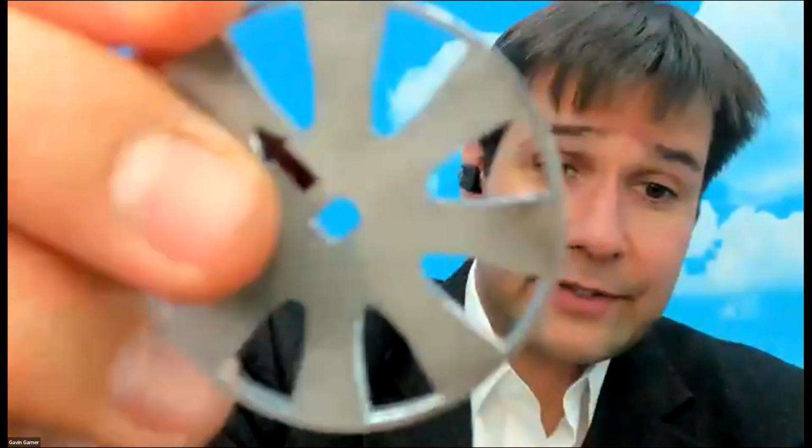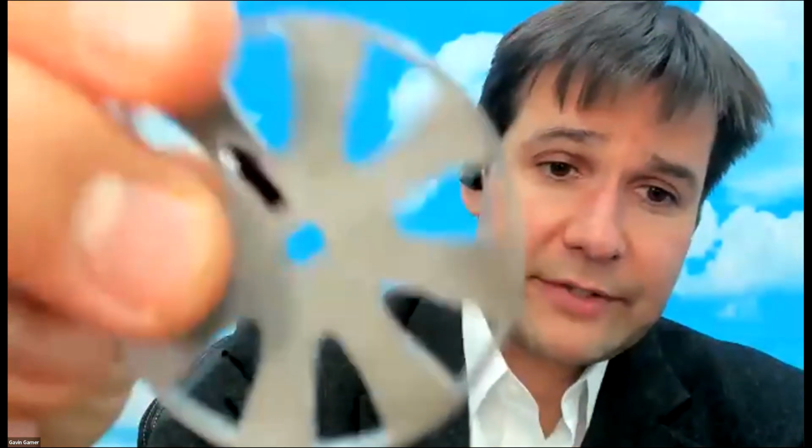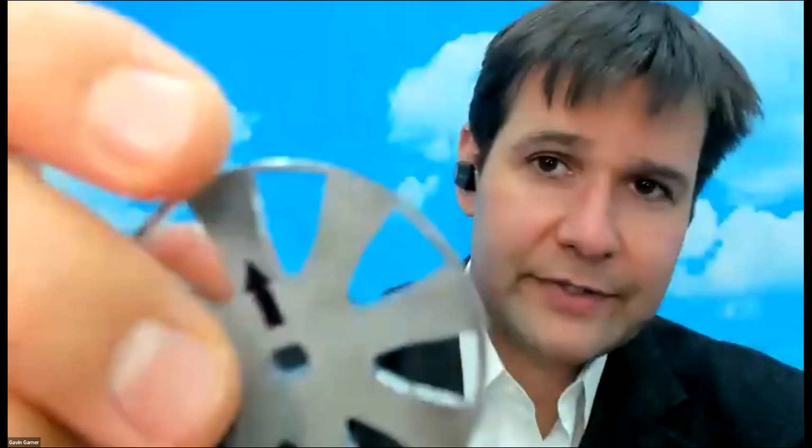How did you cut that on the laser cutter when the illumination might reflect the laser? Yeah, it does, but I'm putting it upside down, so it's got a dull side and a bright side. I definitely don't cut it bright side up. I cut it dull side up, and I'm using a fancy Universal laser.